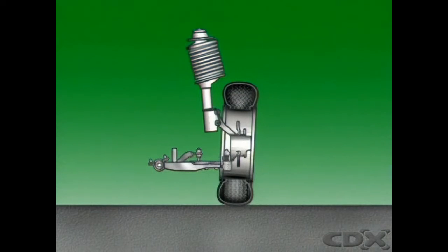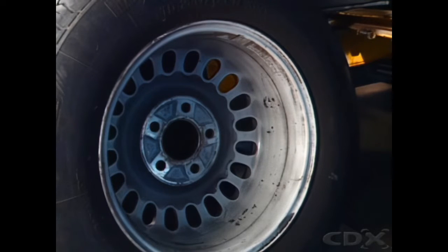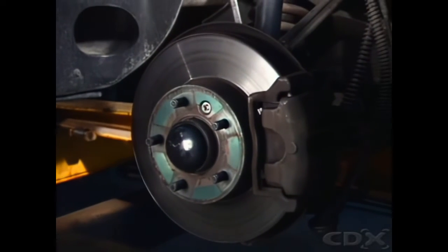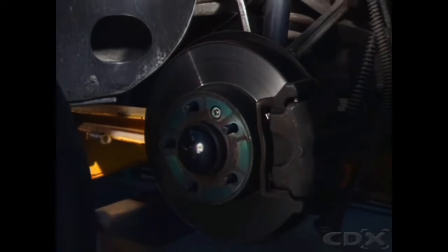Offset is important because it brings the tyre centreline into close alignment with the larger inner hub bearing and reduces load on the stub axle. This allows the inside of the wheel centre to be shaped to provide space for the brake assembly, usually located inside the wheel.